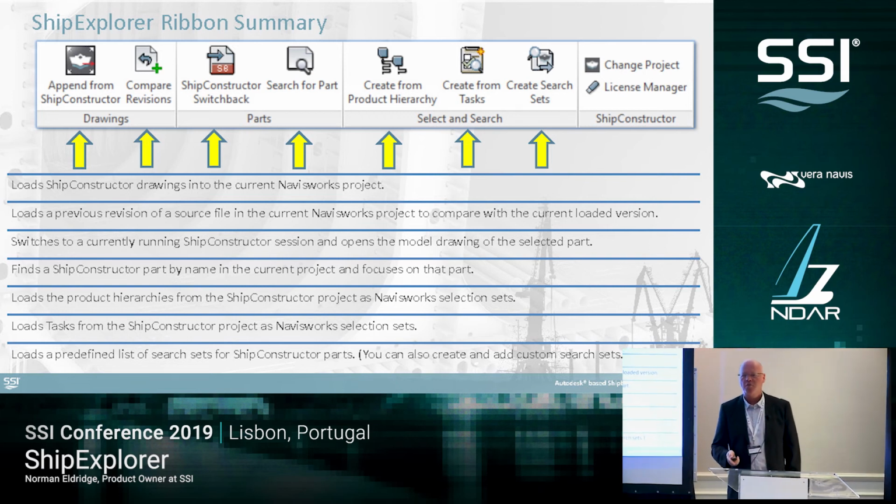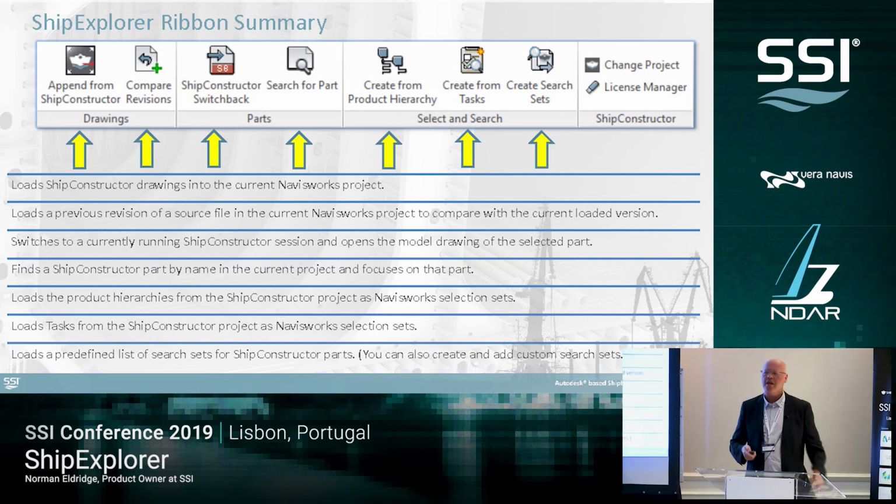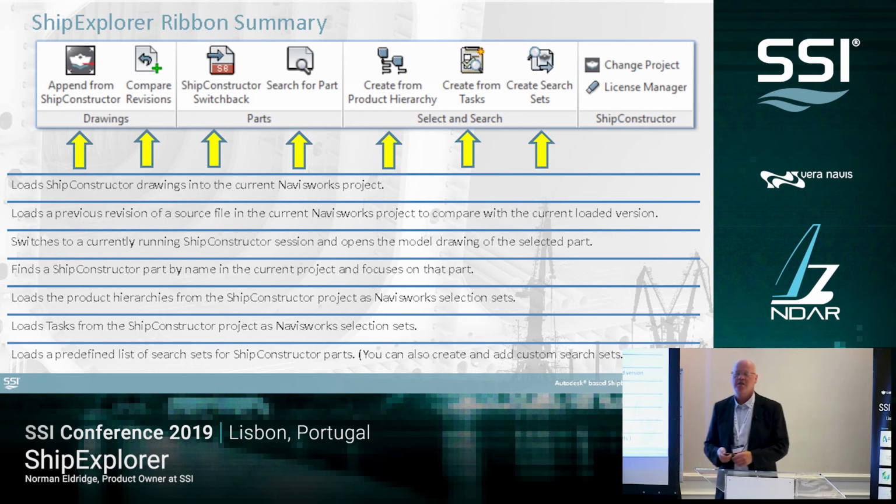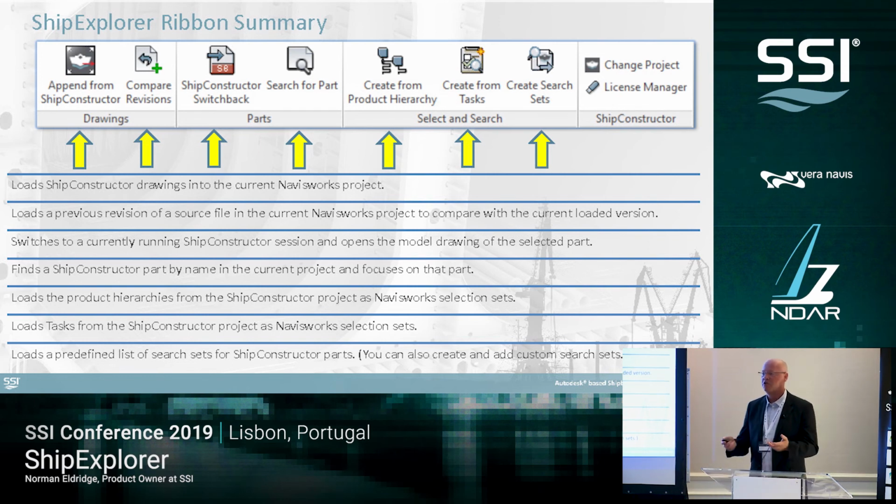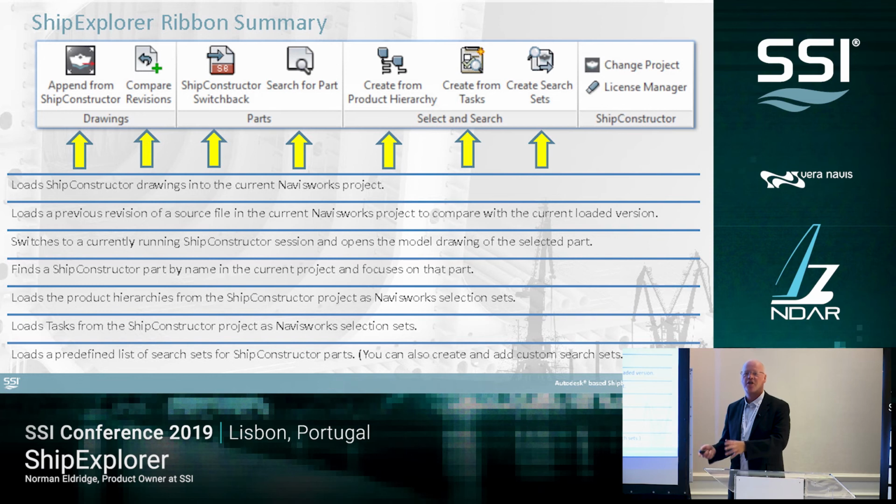ShipConstructor tasks are possible. One of the nice things about tasks, if you enable them in your ShipConstructor project, is that when you set up a task, it records all the information that was changed associated with that task. So then you can actually look at, when you change a part and delete it like Lamberta showed, it really shows you all the things that changed. So when you set up a task for somebody to do some work, now you can go and visualize what did they do in a very quick and easy way. That's where the power of tasks come in here.